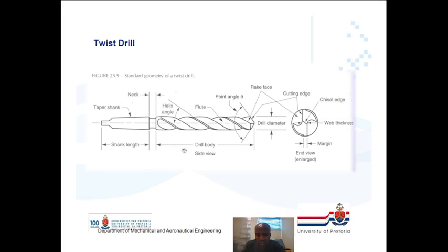So the drill body, that is the length that you can achieve. Otherwise, any length between this and this, you can achieve that. And then you have a drill bit angle there, a pointer angle, and this also determines which type of material you can drill with this drill bit. You have different drill bits for different materials, and speed also plays a very important part. The rotational speed of your drill bit also plays a very important part when you're doing drilling.